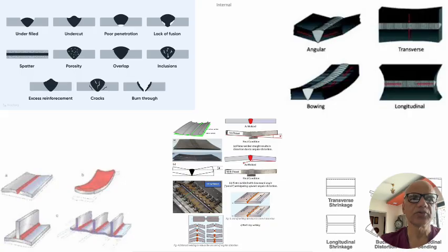In the heated condition you feel as if you have done a good weld, but when it cools down, you see that there is an undercut, sometimes a sharp undercut, which can be a stress riser. So if you happen to see these undercuts after the welding, you need to immediately clean a little bit, grind, make extra space for you to weld, and deposit additional runs to cover it up properly.